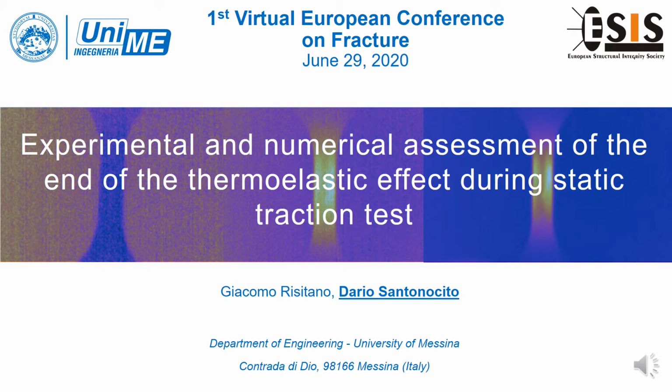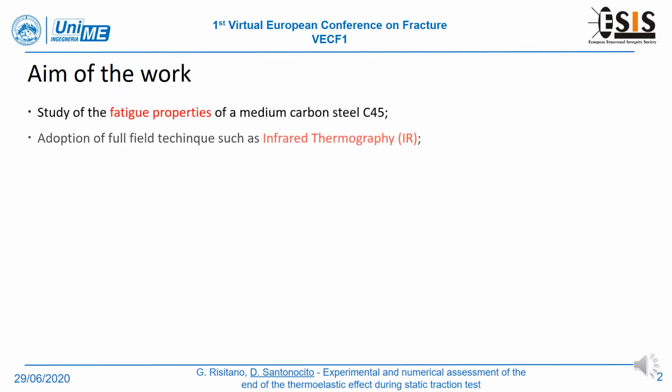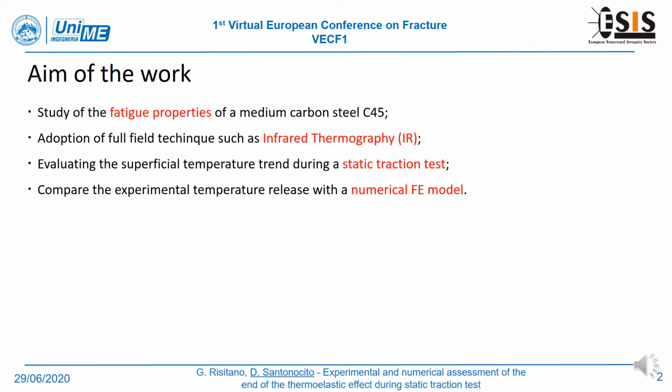This work is entitled Experimental and Numerical Assessment of the End of the Thermoelastic Effect during Static Traction Test. The aim of this work regards the investigation of the fatigue properties of a medium carbon steel, C45, adopting full-field techniques such as infrared thermography.